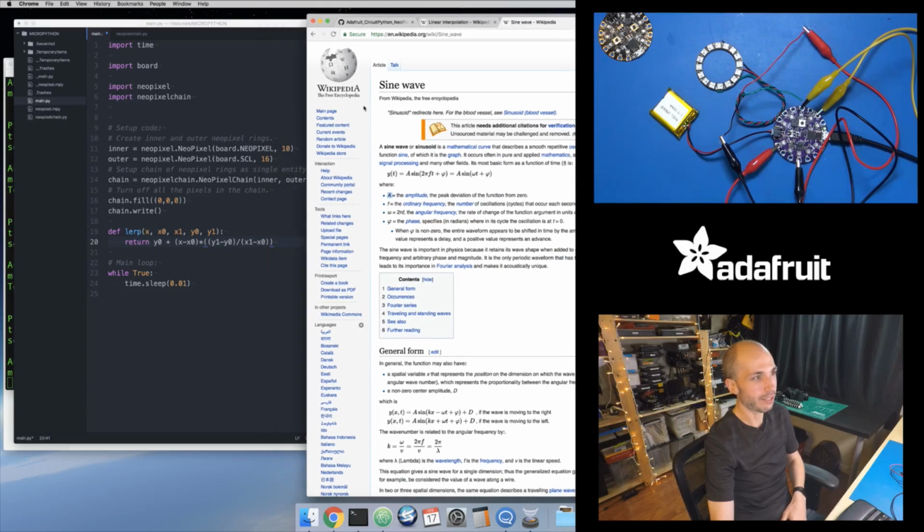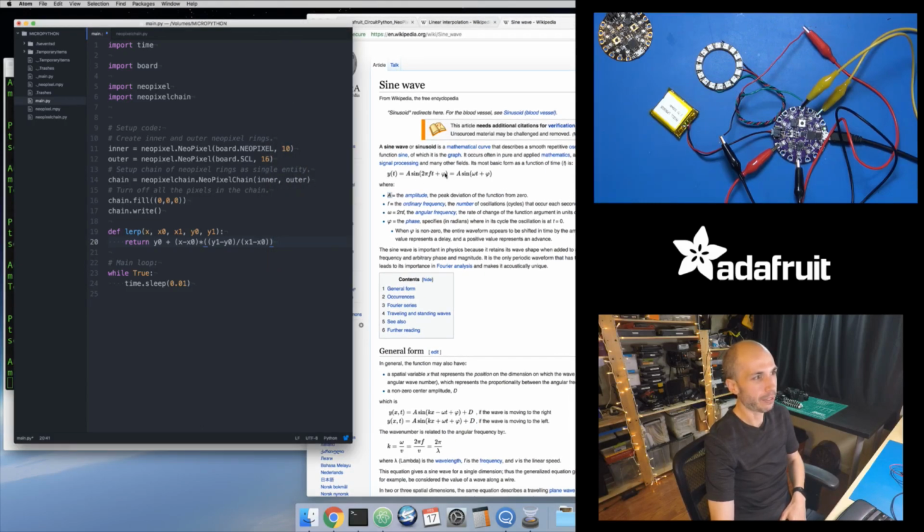But I don't need to use that. I really just need a simple form of this sine wave equation, which is literally just sine of 2 times pi times frequency times my current point in time. So, let's first get my current point in time. In CircuitPython, you want to use the time.monotonic function. Basically this function gives you the time in seconds, but it's not your wall clock time. It's just a timer that's always increasing once a second. And it's a floating point value, so you get millisecond kind of accuracy. This is useful because I don't care that it's 4:45 p.m.